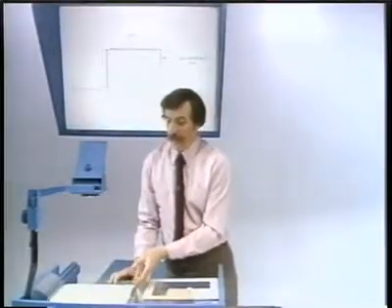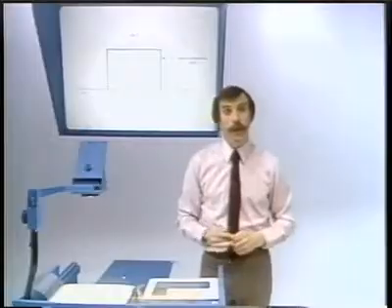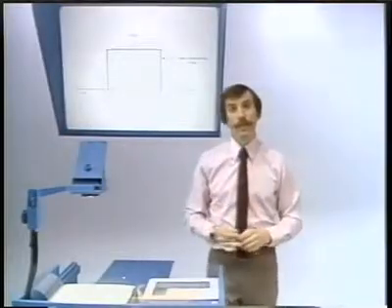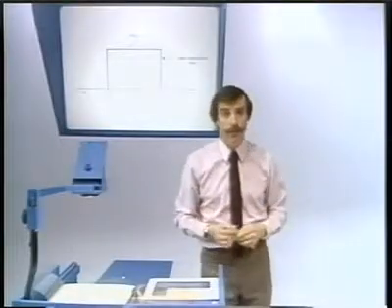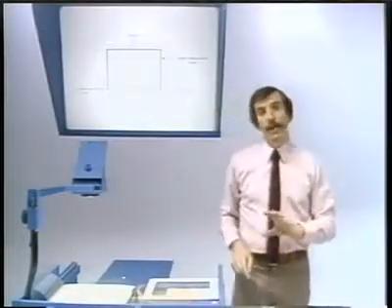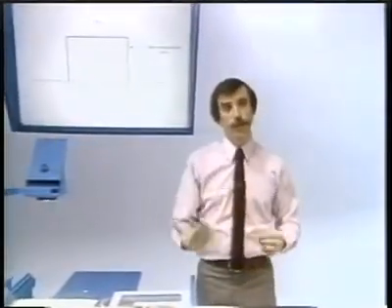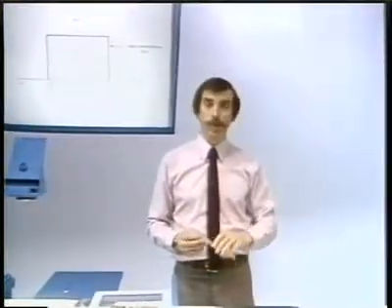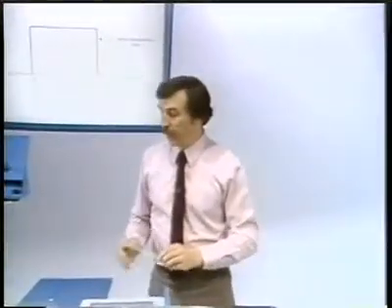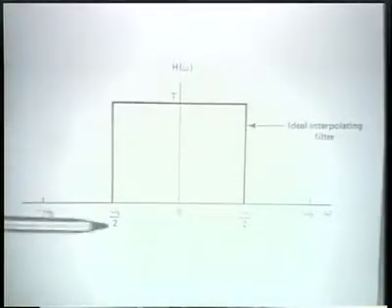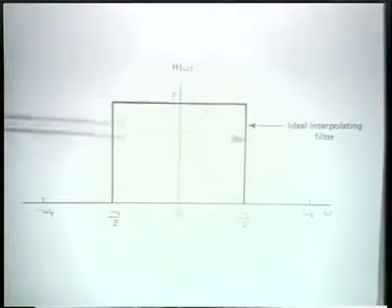Well, in the frequency domain, what we know, of course, is that for exact interpolation, what we want as our interpolating filter is an ideal low-pass filter. Now, keep in mind, by the way, that an ideal low-pass filter is an abstraction, as I've stressed several times in the past. An ideal low-pass filter is a non-causal filter and in fact of infinite extent, which is one of the reasons why in any case we would use some approximation to it. But here what we have is the exact interpolating filter, and that corresponds to an ideal low-pass filter.